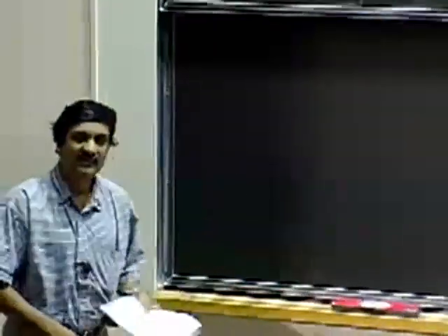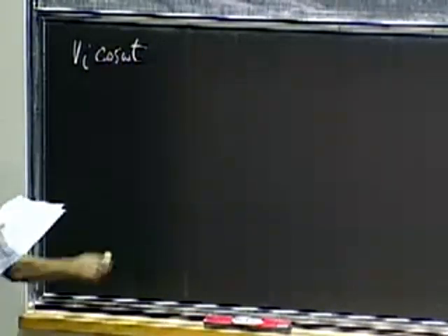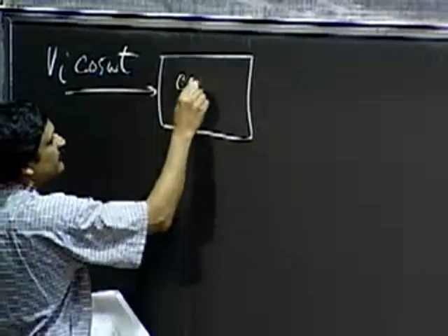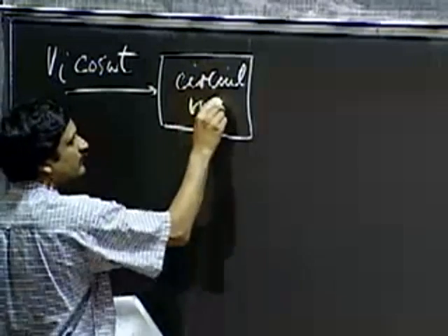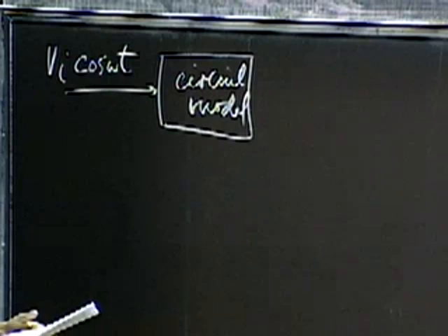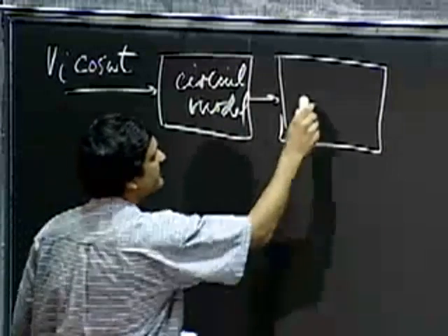So what I'll do is let me draw a little chart for you to sort of visualize the various processes we've been going through. So we can liken obtaining the sinusoidal steady state response to following these steps. So here's my input, and what I did as a first step was fed my input to a usual circuit model. Okay, my elements were lumped elements, built the circuit, and wrote down the VI relationships for the element. As a second step, I set up the differential equation.